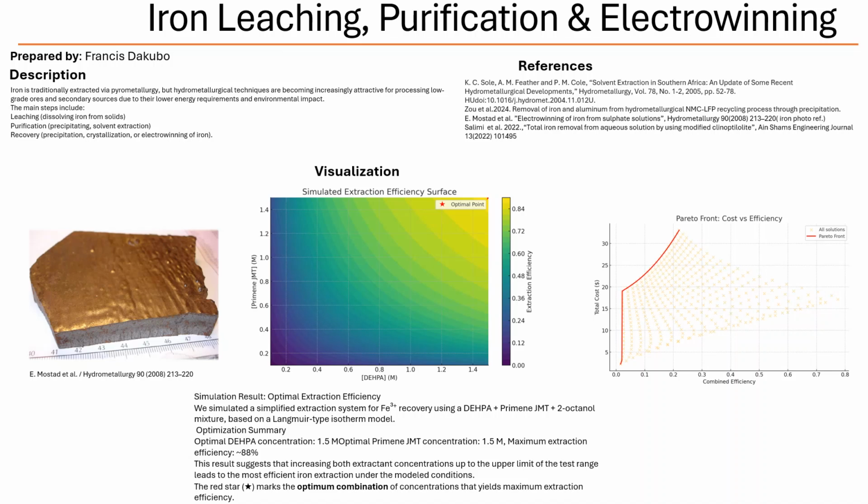pH, again, always a factor. What were the specific findings regarding pH in this process? They found that below pH 2, the current yield took a hit. But above pH 2.75, the iron deposit started getting rough, with dendrites and oxide inclusions, so they had to keep it in a narrow range to get both good efficiency and good quality. A delicate balance. What about the current density and temperature?